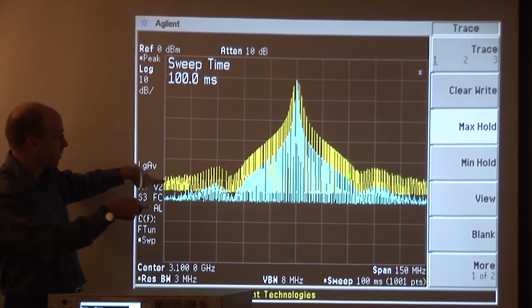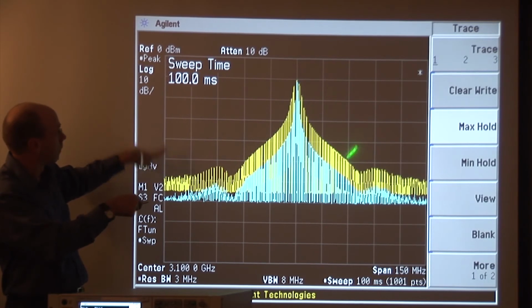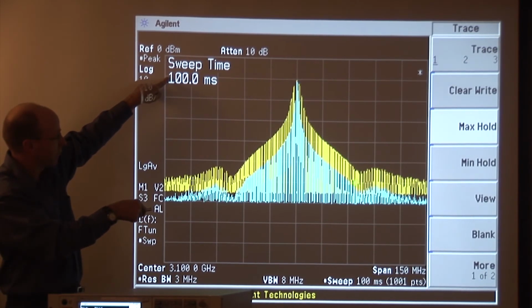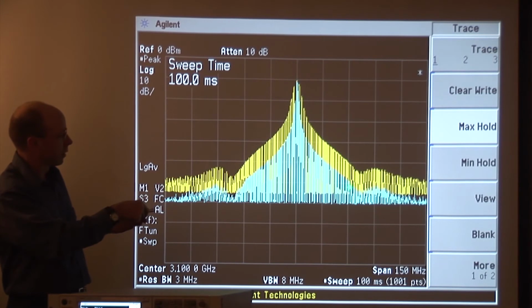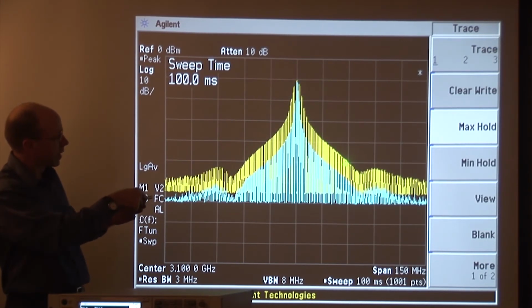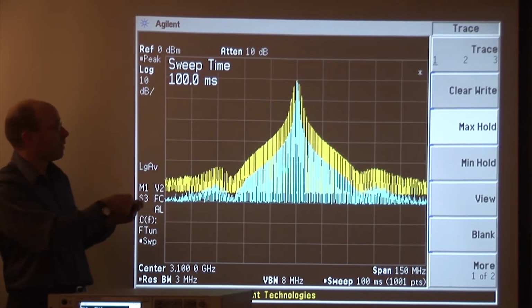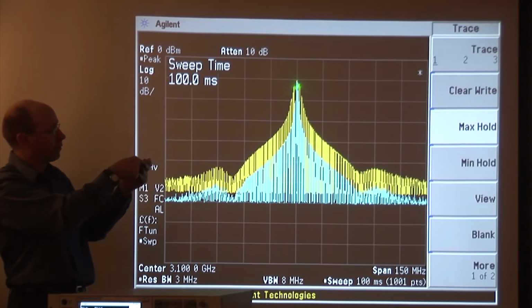And on that same frequency, in another bandwidth, that level is only, oh, sorry, I misspoke. Go from here, yeah. 10, 20, 30, 40, 50. Okay, at that frequency right there, in the 1 megahertz bandwidth, the emissions are 50 dB down, and in this second bandwidth of 3 megahertz, the emissions are only 40 dB down. So you don't get a fixed amount of delta between a power level that you measure at a frequency in the spurious spectrum versus the power at the fundamental.